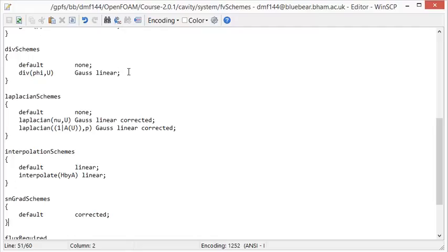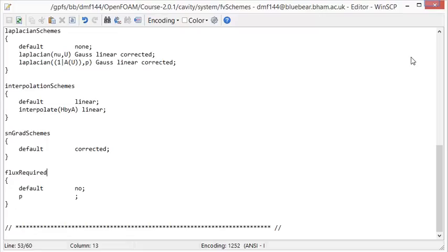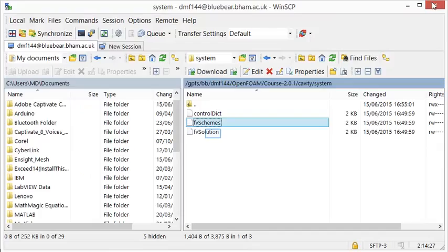Gaussian integration is based on summing values on cell faces, which must be interpolated from cell centers. The Laplacian terms are discretized using the second-order central difference schemes. The specification of the linear equation solvers, tolerances and other algorithm controls is made in the fvSolution file.